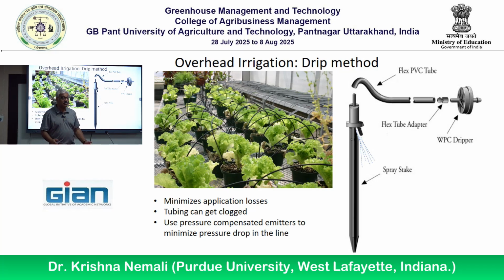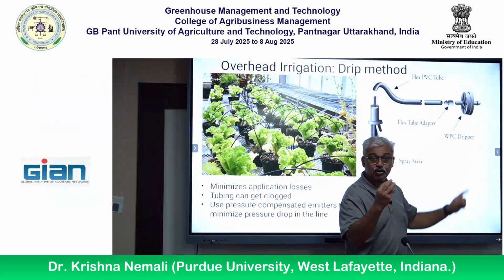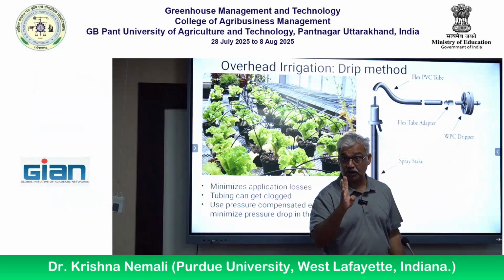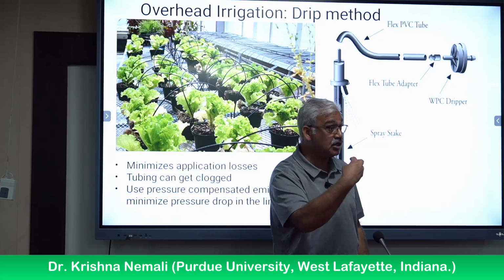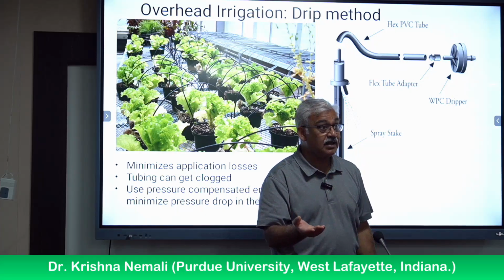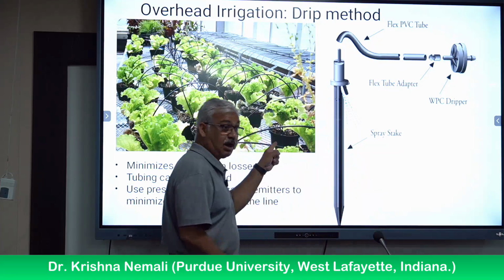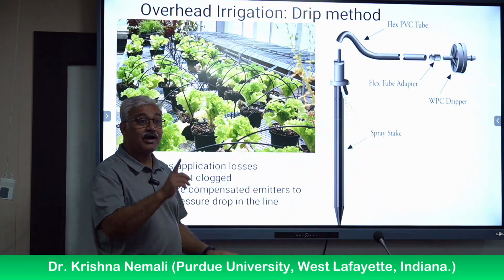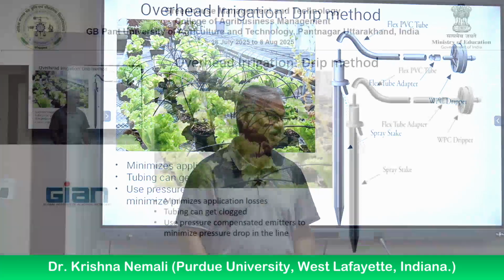25 liters per hour. But let's say you want to add only 1 liter per pot every day. You can easily do that. How do you do that? What do you adjust? So again, let me explain. This drip emitter capacity is 100 liters per hour, but I put a manifold. The manifold has 4 outlets. So how much is flowing through each outlet? 25 liters per hour. But I don't want 25 liters in that pot. It's a small pot. I'll kill the plant. I only want to add 1 liter every day. How do I do that?